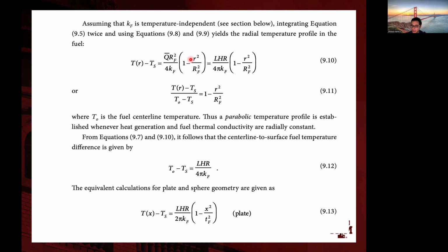But basically, as we will see when we look into the input file, this is the analytical solution that we will compare against. So we can actually type this analytical solution inside the Moose input file and ask Moose to take the difference between this exact analytical solution and the approximate numerical solution that Moose calculates when we run the input file.